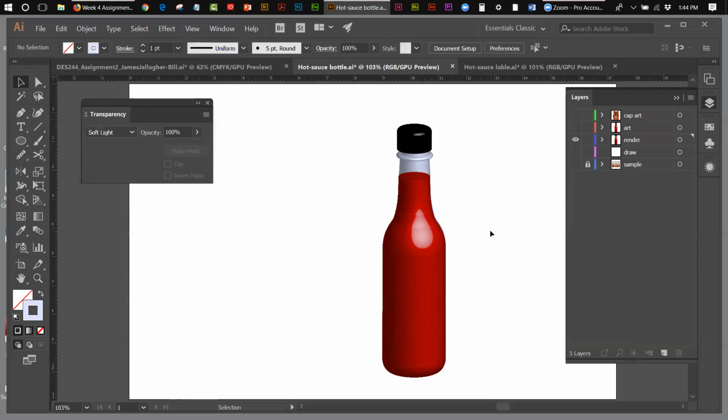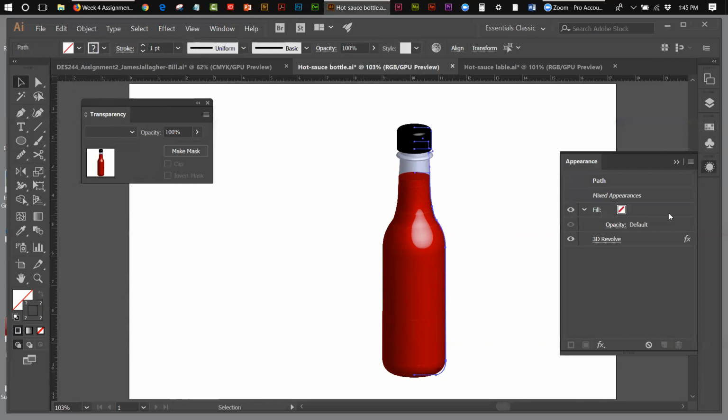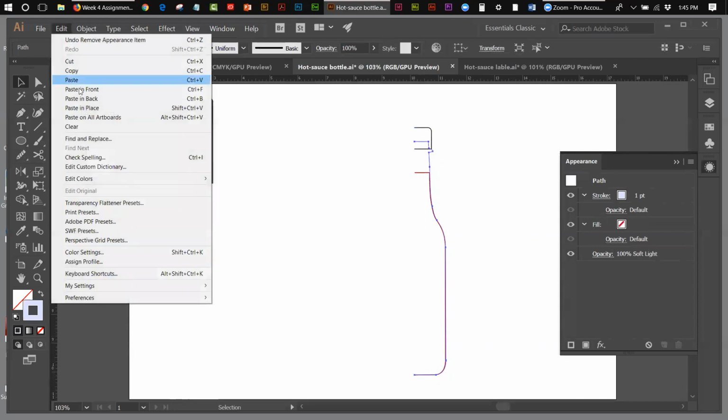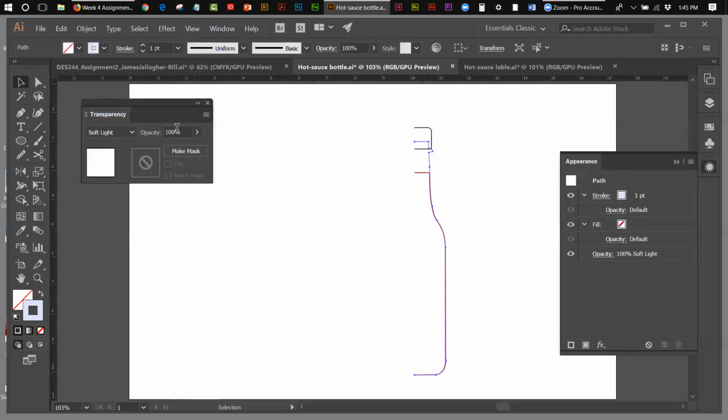So basically what I want to do is finish this. So I'm going to select this, and go to my Appearance panel, and take my 3D Revolve and delete it, okay? And one more thing I'm going to do is select this guy again. I'm going to go Edit, Copy, Edit, Paste in Place, all right? And then I'm going to move it over a little bit to about right there.